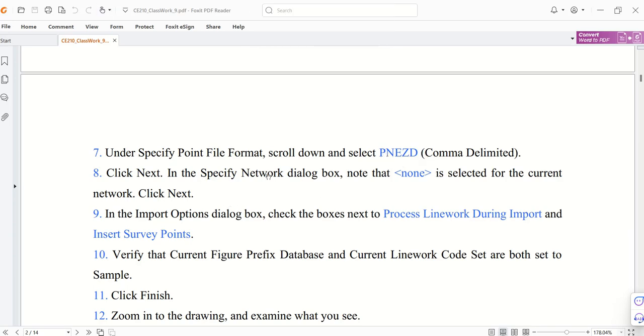So this is the format, and they are telling you to process the line work. This is an important detail in Civil 3D. In reality, when you import a point file, if you define the description keys for your points, Civil 3D will know. You should inform it from the beginning, before importing the database, that this is a tree, this is a manhole, this is a benchmark. Like this, when you import the point file, they will appear as wanted.